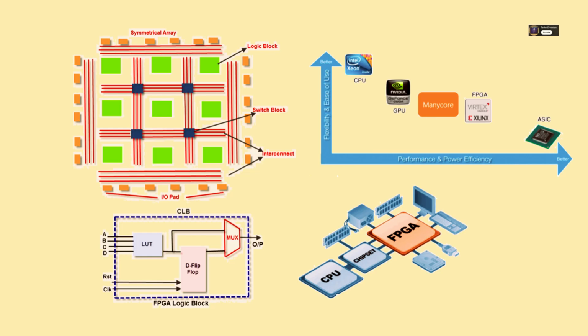The FPGA is the reconfigurable customizer. Instead of executing sequential software instructions, you are literally programming the logic gates themselves, the connections between them, after the chip's been made. Wow. So the task you design runs in parallel inherently because you're creating a dedicated hardware path just for that calculation. And the payoff is ultra low latency for specific things like, say, digital signal processing.